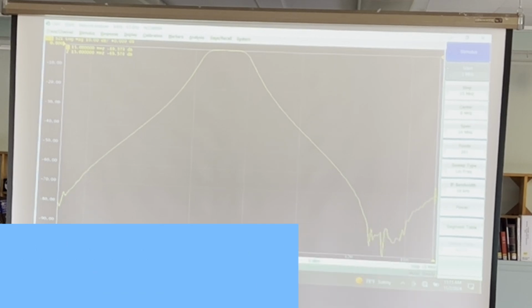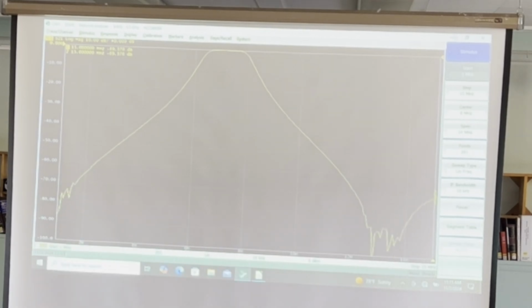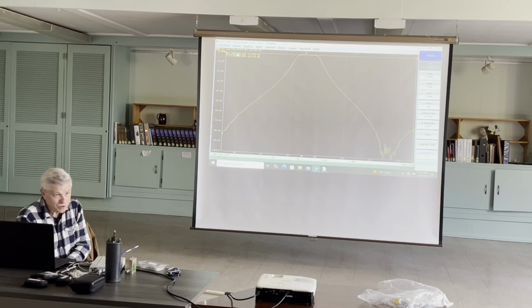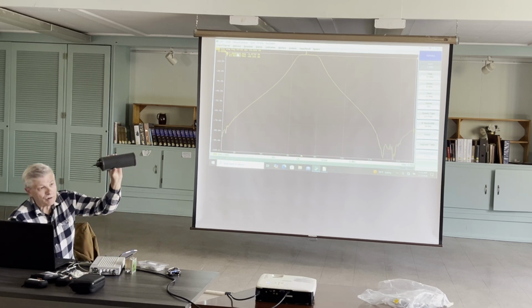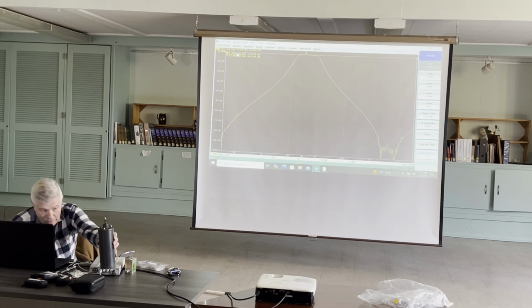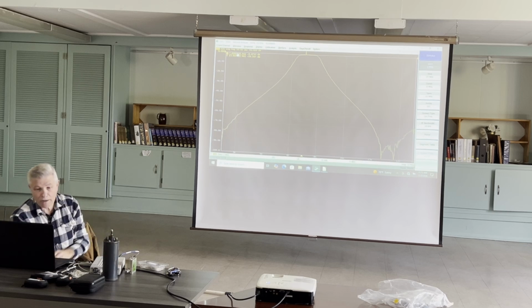Let's go right on. Let's do 7 megahertz. Let's put in a marker on 7 meg. I would expect that from anything that's in the HF band. You're going to have more attenuation with something like this because you're up at 450. Obviously, this is just the physics of how it all works. But that's a pretty good looking filter.